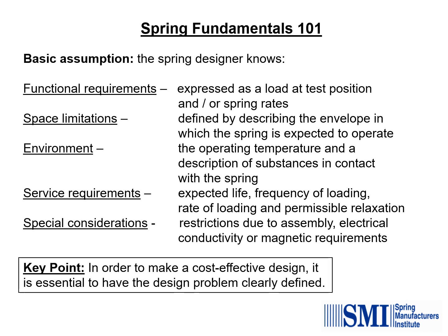Let's review. Basic assumption, the spring designer knows. Functional requirements, expressed as a load at test position and or spring rates. Space limitations, defined by describing the envelope in which the spring is expected to operate. Environment, the operating temperature and a description of substances in contact with the spring. Service requirements, expected life, frequency of loading, rate of loading, and permissible relaxation. Special considerations, restrictions due to assembly, electrical conductivity or magnetic requirements.